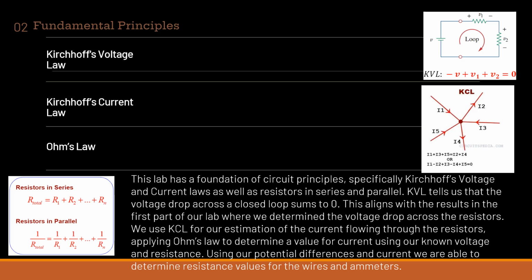The big fundamental principles of this lab are Kirchhoff's voltage law, Kirchhoff's current law, and Ohm's law. This lab has a foundation in circuit principles, specifically Kirchhoff's voltage and current laws, as well as resistors in series and parallel. As you can see in the figure on the left, the total resistance for resistors in series and the total resistance for resistors in parallel.